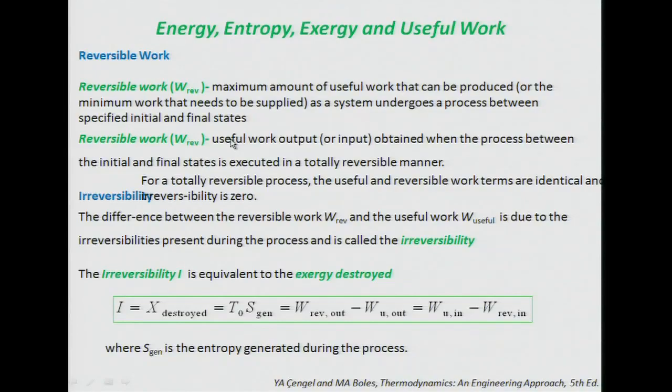So reversible work is useful work output or input obtained when the process between the initial and final states is executed in a totally reversible manner. Okay? So useful and reversible work terms are identical. Right? Reversible work, there's no irreversibilities. I don't lose anything. So irreversibility is the difference between the useful work and the reversible work. And that irreversibility is equal to the amount of exergy we destroyed.